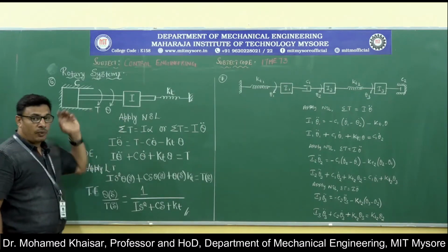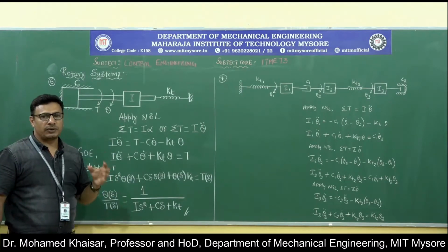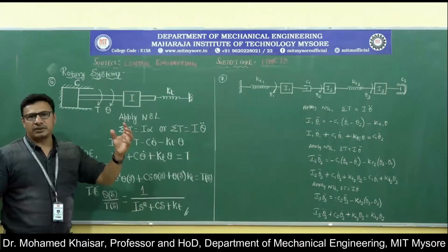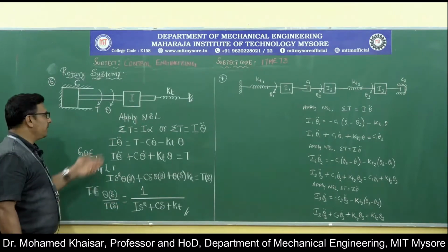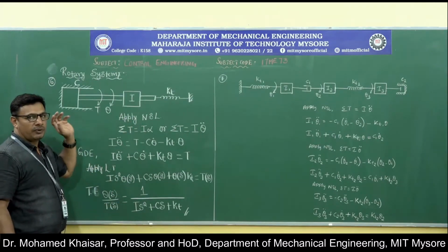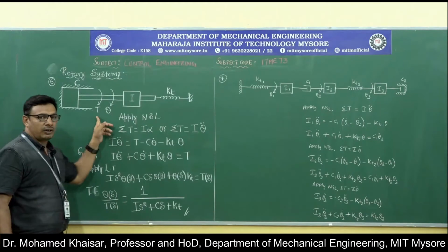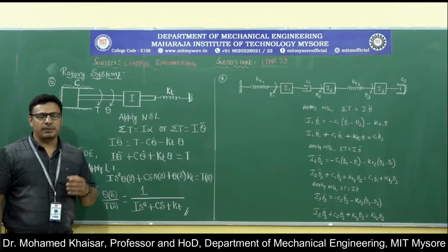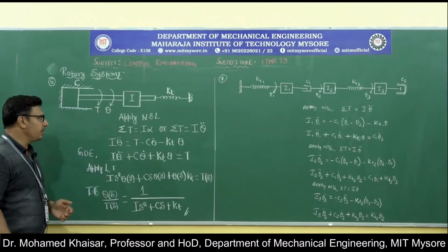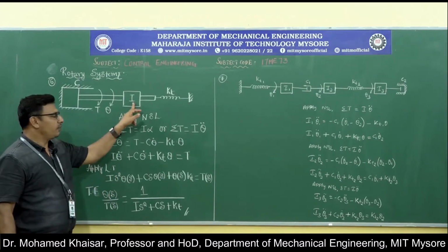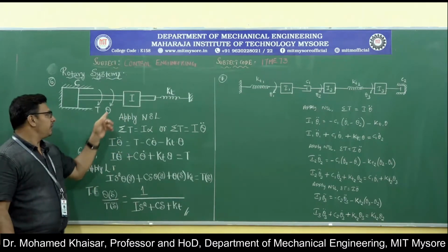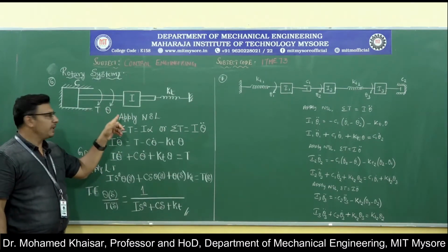Now, the force which was disturbing, the force responsible for displacing the mass by some distance x or y, in the rotary system will be replaced by the torque. So if you see the similar terms compared to the linear system and the rotary system, in place of mass we will be considering I, and in place of the displacement x or y, we will be considering the angular displacement, that is theta.